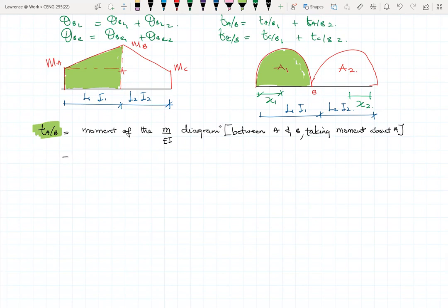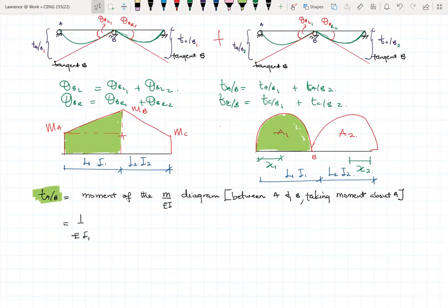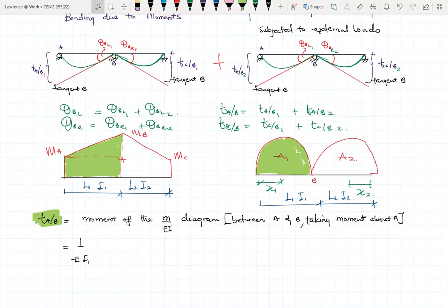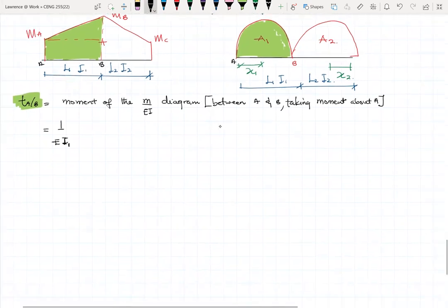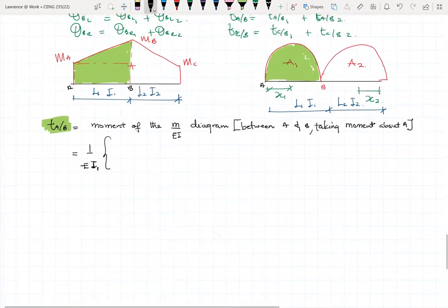Okay, all right. So I'm dividing everything here by EI, so I can bring that one out of the equal to sign. In this case, I'm looking at I1 because I'm focusing on the sections between A and B. So that's where the I1 L1 is, between A and B. So E over I1, I'm assuming that the E is constant throughout. So this will multiply that.